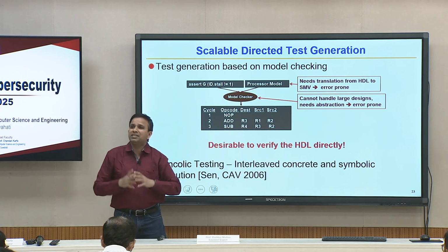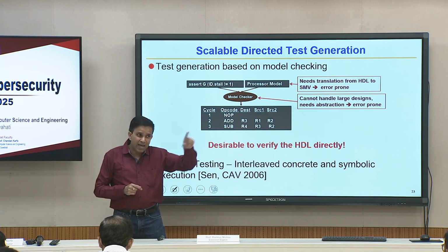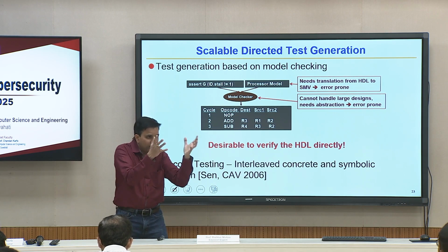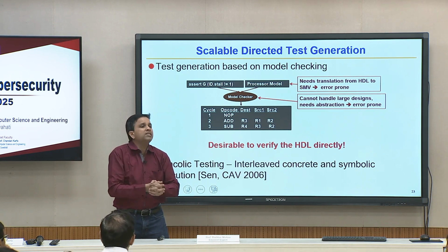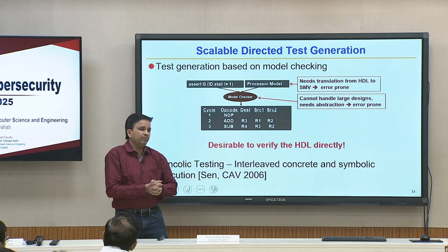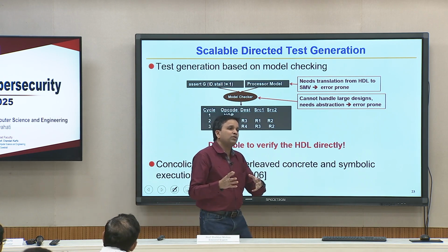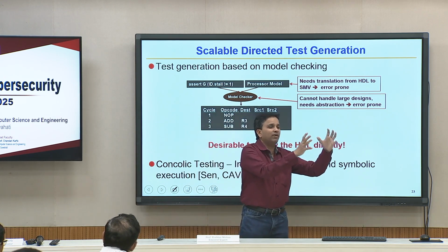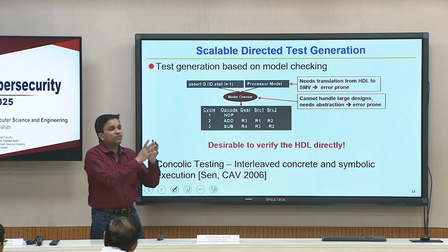And let us say you guarantee something. What you guaranteed is on that formal model, not the actual model, and the actual VHDL or Verilog design would be synthesized. So it is kind of a serious problem. We can argue that the formal model was automatically generated from the Verilog or VHDL, but it is still a translation.